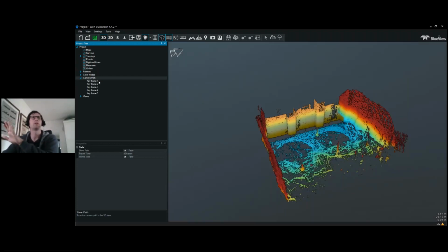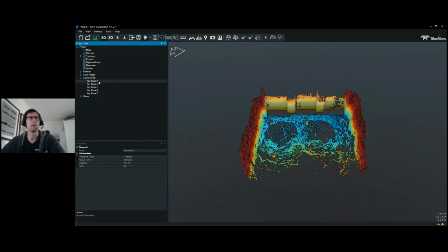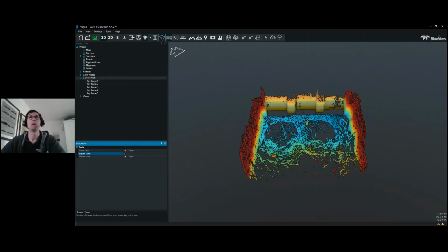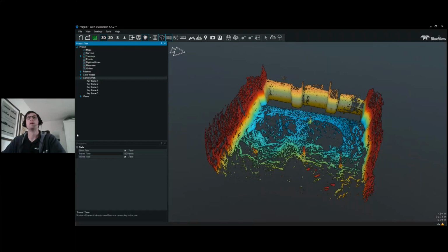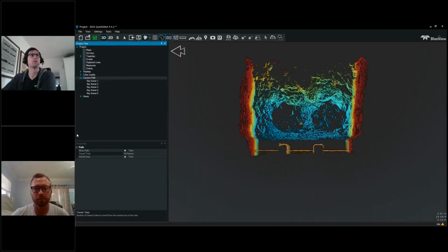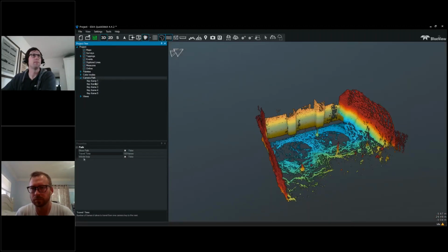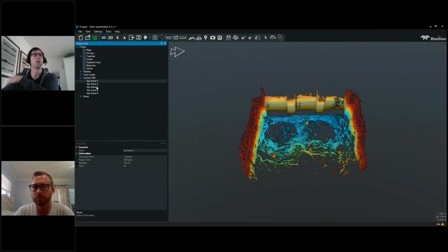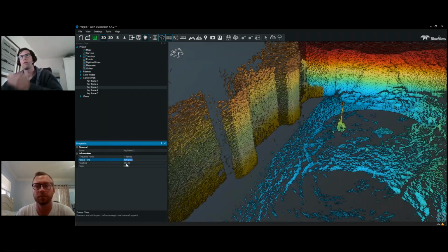I can set any number of parameters. I can set the overall speed, travel time here. So if that was too quick, I can slow it down and say, okay, let's take maybe 150 frames to travel the entire path. Now if I cycle it again, it's going to move much slower, which makes more sense. Generally, you don't want it flying through the point cloud too quickly. So that's travel time. For each individual point, you can have a pause time. If I wanted it to pause on this wall for longer, instead of just 20 frames, let's pause here for 50 frames. It's just going to pause in this location a little longer.